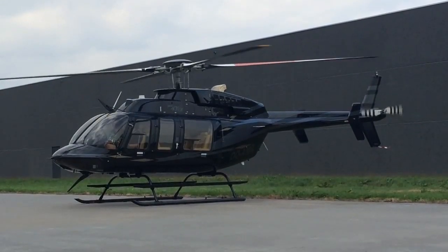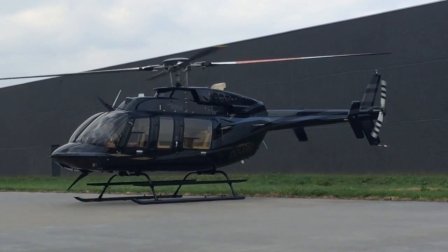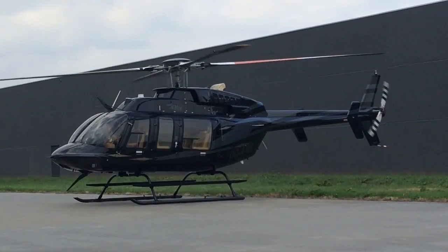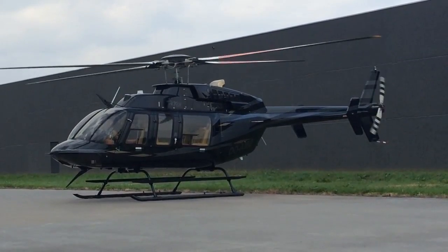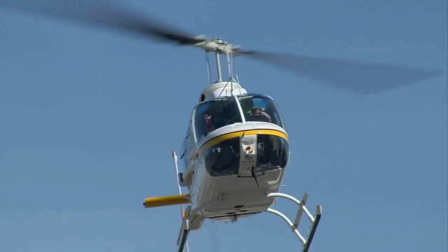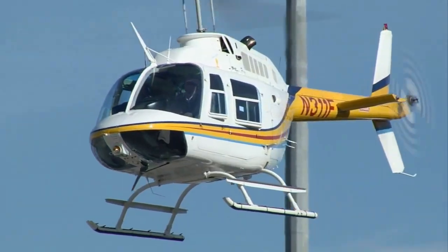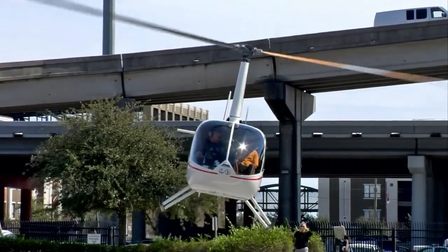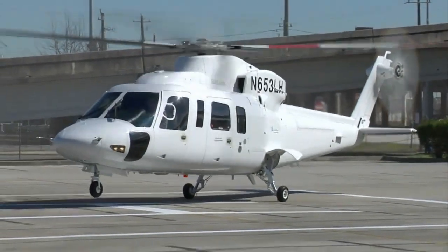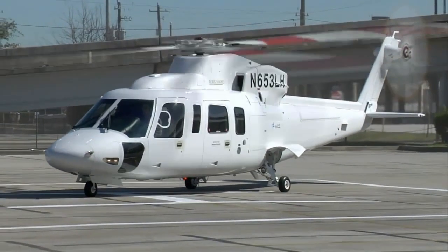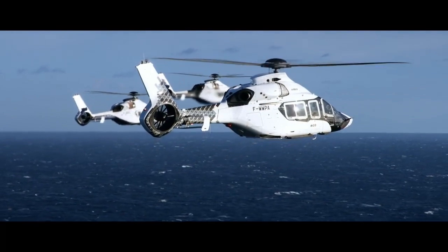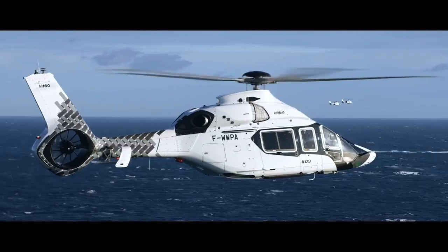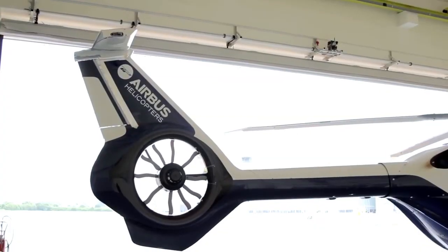The tail rotor is a smaller rotor mounted so that it rotates vertically or near vertically at the end of the tail of a traditional single-rotor helicopter. The tail rotor's position and distance from the center of gravity allow it to develop thrust in a direction opposite of the main rotor's rotation to counter the torque effect created by the main rotor. Fenestron and fantail are trademarks for a duct fan mounted at the end of the tail boom of the helicopter and used in place of a tail rotor.